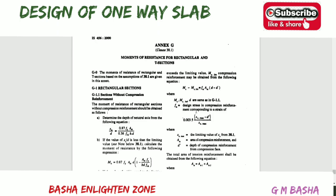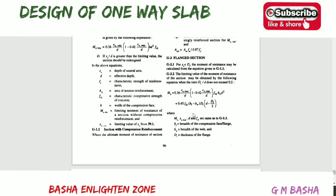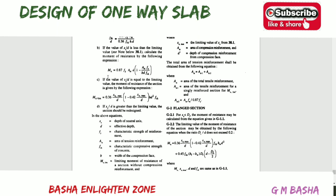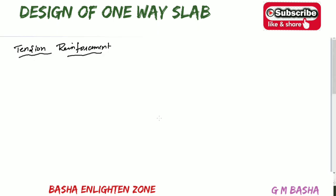See here in this code book, the page number will be 96. It is better to write it down there also. On page number 96 there is one formula: Mu equal to 0.87 Fy area of the steel d into 1 minus Ast Fy by fck bd. So take down this formula for finding the tension reinforcement.